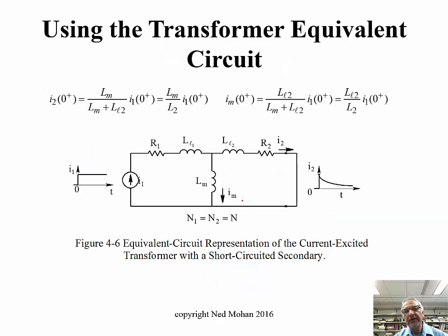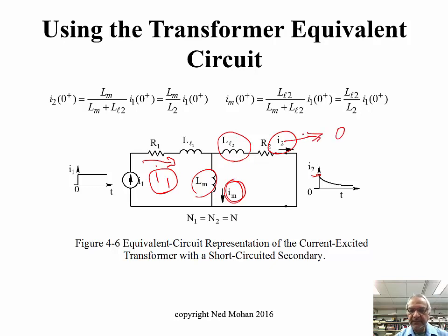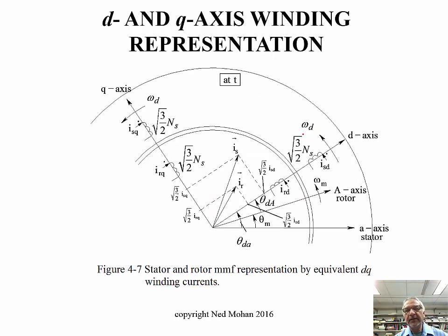Okay, so you can also see it with a transformer equivalent circuit analogy, but really a circuit type analogy, that when you make the change in this current I1 over here, this current splits into two parts, I2 and IM, and initially this leakage is much smaller than this, so I2 reaches this value here, but slowly this I2 decays out, and eventually this IM would become equal to I1, and this I2 would go to 0. Okay, so that's what will happen in this circuit here. Okay, so let's go on to the machine. That is our main concern.